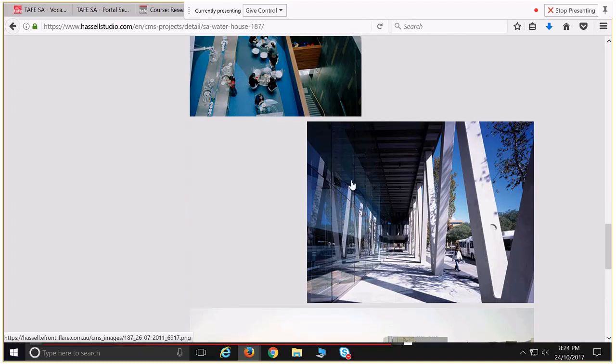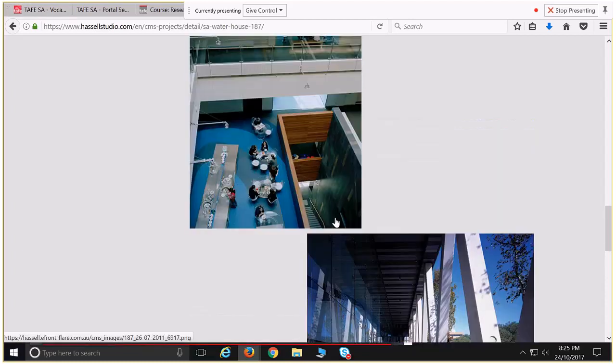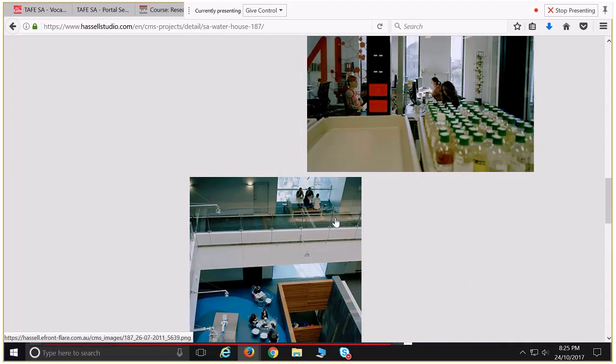And then large sections of curtain wall glazing at the bottom floor. And this one has actually got glazed mullions. It's very hard to see, but can you see this little strip here? There, that's a slightly different colour as you're looking through it. That is a glazed mullion. And so rather than have an aluminium mullion there, we have a plate of glass, and that is fixed onto the glass.